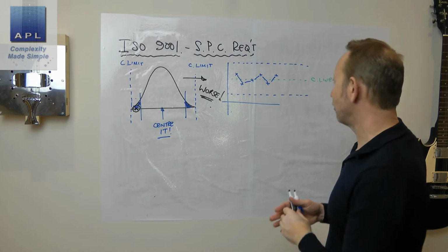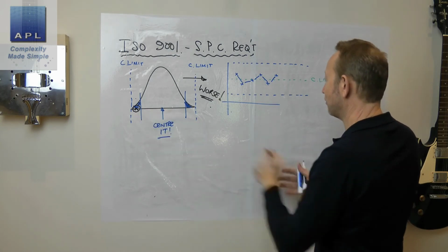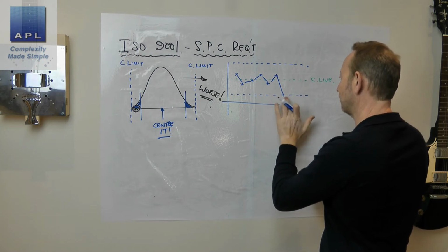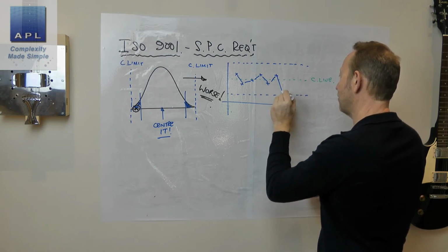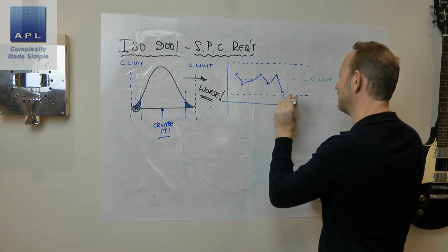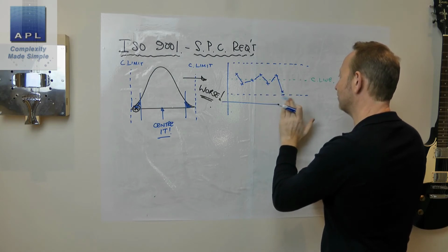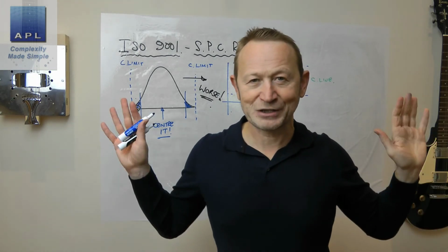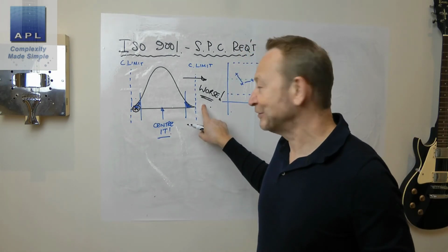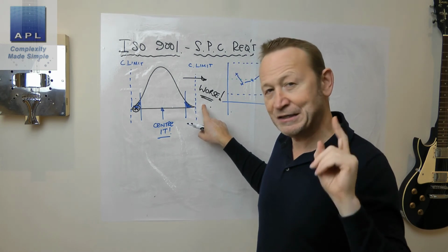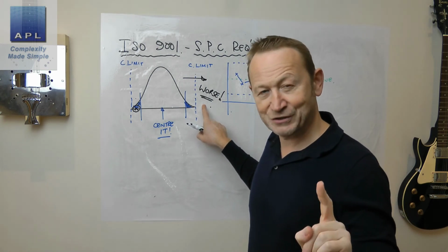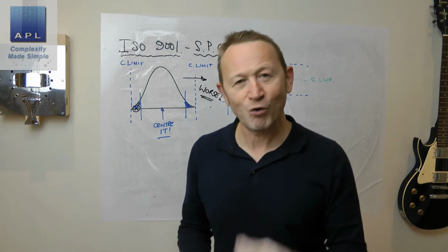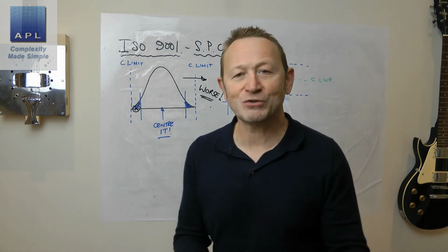What an SPC chart, of course, will do, it'll see this data point here. It'll see it outside the tolerance, but inside the control limit. And because it's inside the control limit, he'll keep his hands off and he'll never make this mistake. He can only do that with an SPC chart. This is always appropriate, because what's the alternative?